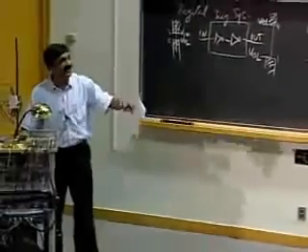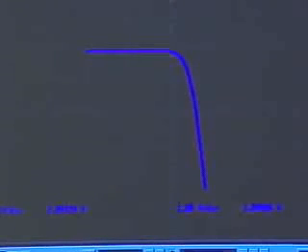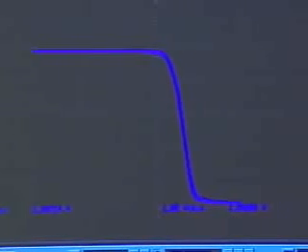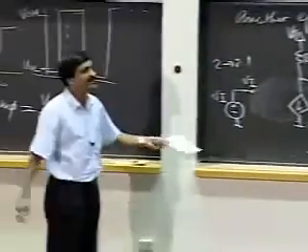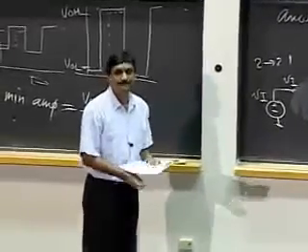Notice that for that device, mathematically, just by that model, it should just have gone through the floor and punched through to the corridor below. But this is a practical device, and notice that the model breaks down, and that's what begins to happen. The device stops behaving like a dependent current source. Rather, it behaves like some corny old resistor and saturates out.